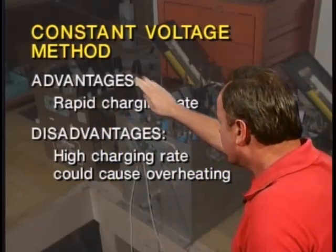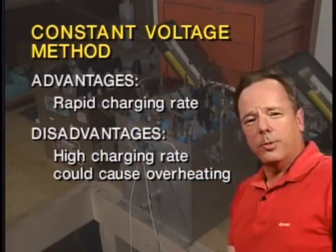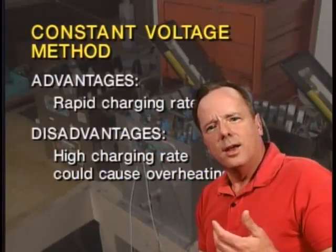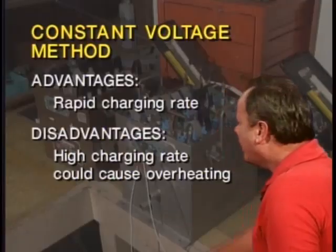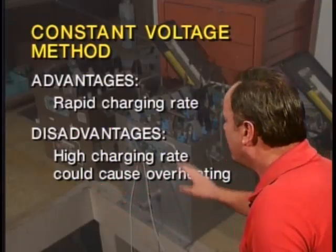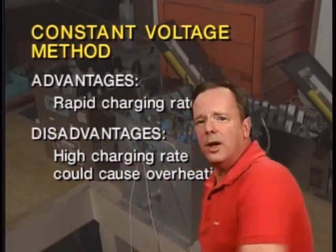Now the advantage of the constant voltage method is that you get a very rapid charging rate, particularly when the battery is very discharged. However, the disadvantage is if you have a NiCad battery, that very high charging rate could actually cause the battery to overheat. So that's both the advantage and disadvantage of the constant voltage method because you're not really controlling the rate that you're charging the battery.